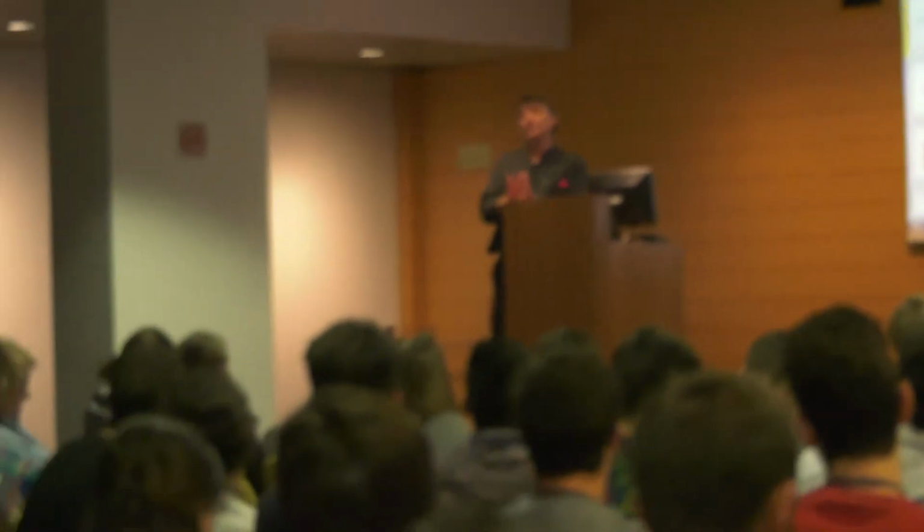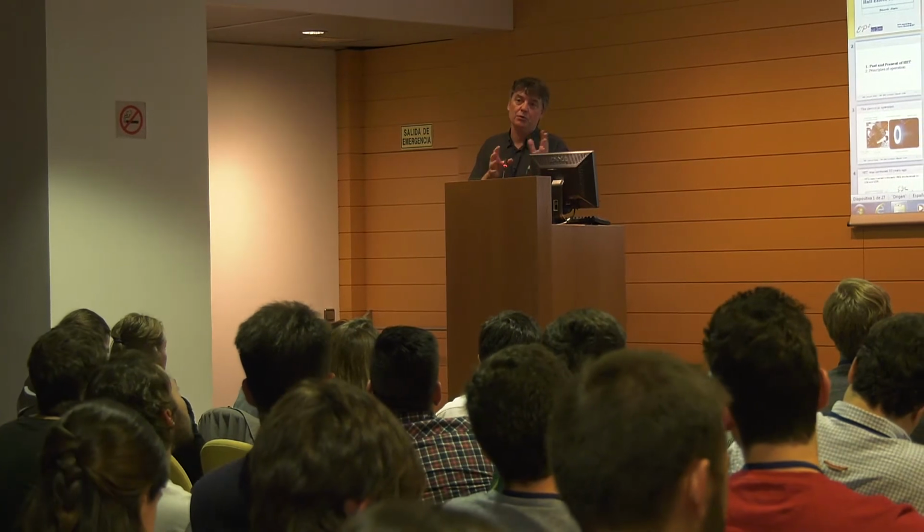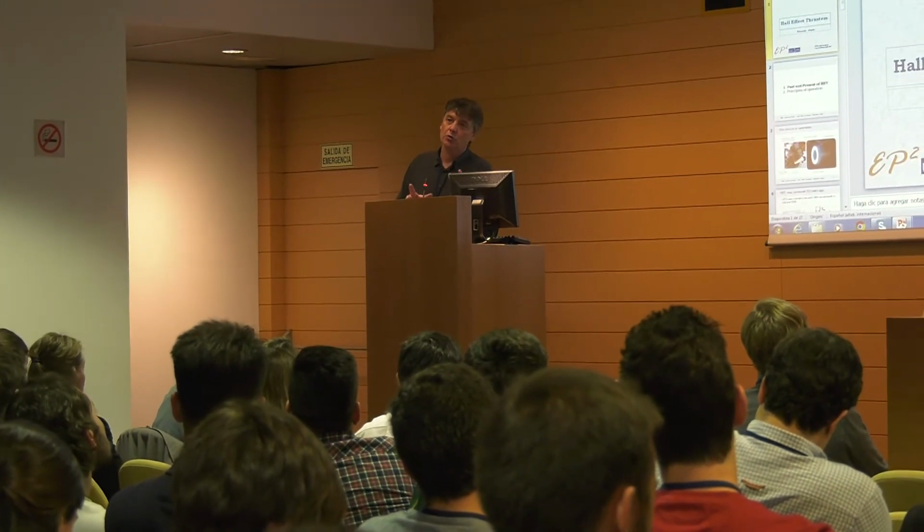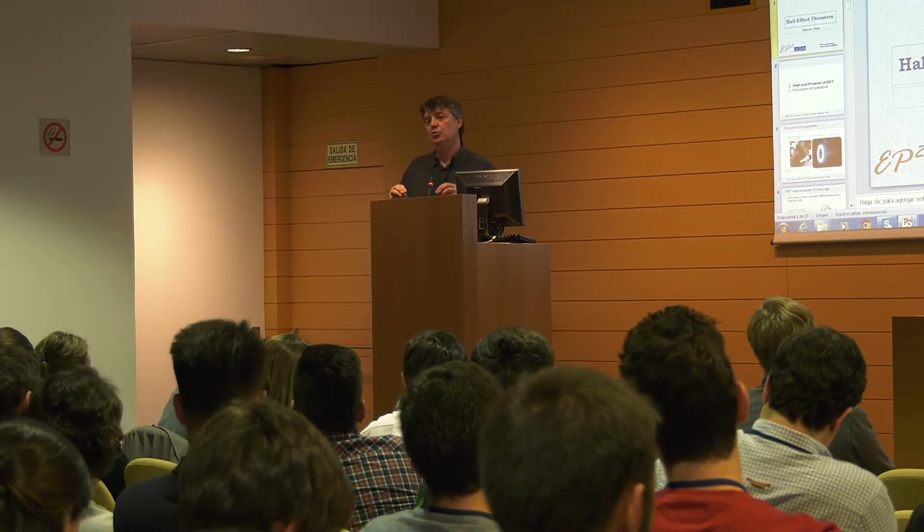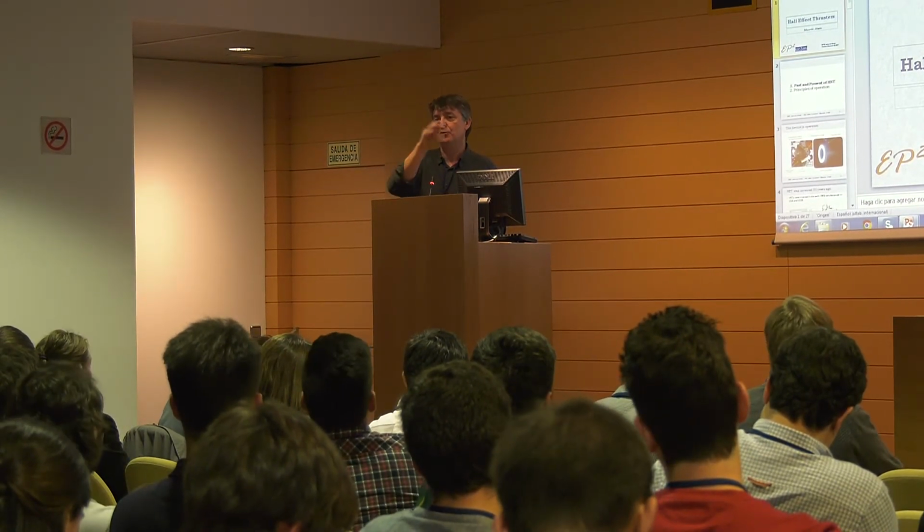CFD does not work because this is not a collisional fluid, okay? So classical fluid equations do not work, we have to add equations. MHD, that is close to CFD, usually is not used for Hall thrusters. So you have what is called the multi-fluid approach. You treat electrons as one fluid, ions as another, neutrals as another, and then you have some interaction between these fluids. Usually you cannot get much detail. It's difficult to have a full model of that, okay? There are 1D, quasi-1D, but you don't have 2D models of that. Well, no, there is one. Now, there is one 2D fluid model that is working on Hall thrusters, okay?